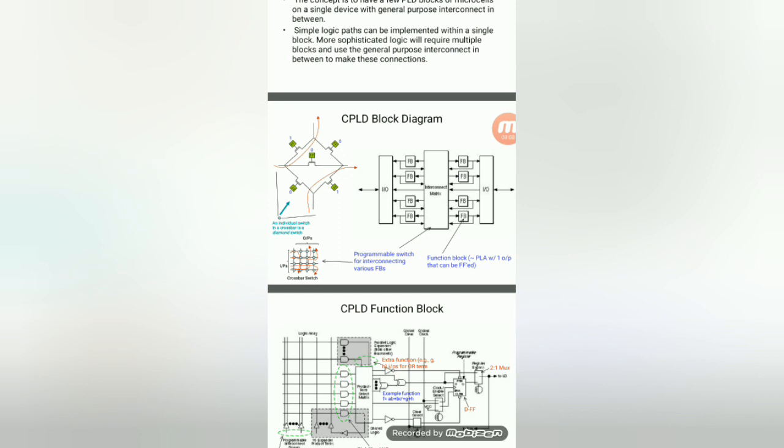The interconnect matrix is established by using a crossbar switch. The internal circuit of the crossbar switch is shown in the figure: FETs connected in a star shape. Based on our requirement, a particular transistor will turn on, so the signal will transfer left, right, straight, front or back, as seen from the arrow marks in the figure.